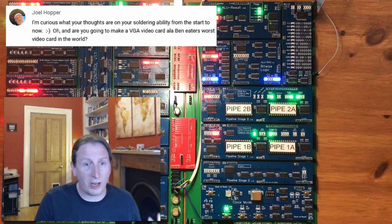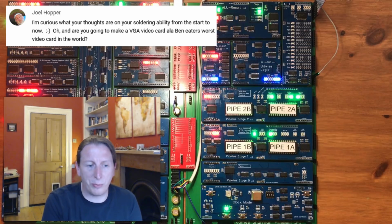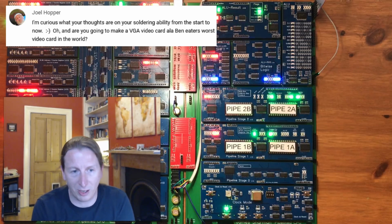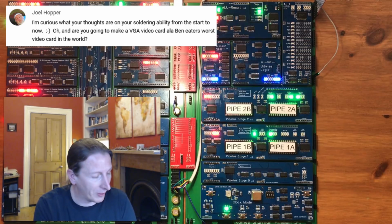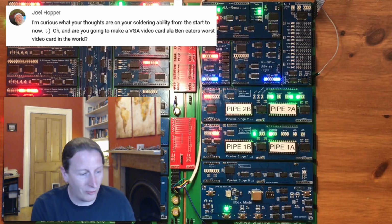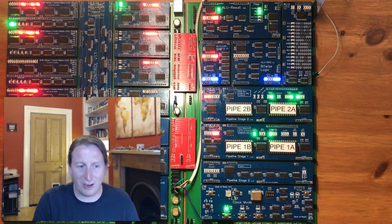Well, my soldering's definitely got better from the start, particularly when I was doing all the hand soldering right at the beginning. I made a lot of mistakes, which I tend not to make now. Even very simple things like putting on components the wrong way around, it's just a habit you need to form, to actually check the right things at the right time. More recently, I've been doing the hot air stuff with the stencil to apply solder paste, and that produces much cleaner, much nicer results. But if I look closely, it's very obvious to me which areas of the board I had to touch back up, because the hand soldering just doesn't produce as good results as that. So yeah, that moved forward quite nicely.